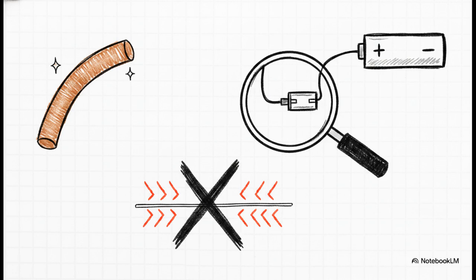First, always use freely available online charts to match your wire gauge to your amp load and distance. Oh, and make sure you're using pure copper wire. Aluminum just can't handle the same loads. Second, size that fuse to 125% of your appliance's amp rating. Third, always connect the fuse on the positive wire as close to the battery's positive terminal as humanly possible. This protects the maximum length of wire.